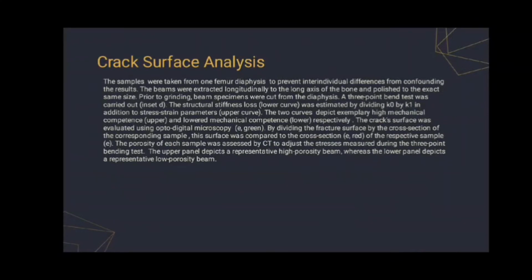Crack surface analysis. The samples were taken from one femur diaphysis to prevent inter-individual differences from confounding the results. The beams were extracted longitudinally to the long axis of the bone and polished to the exact same size. Prior to grinding, beam specimens were cut from the diaphysis.